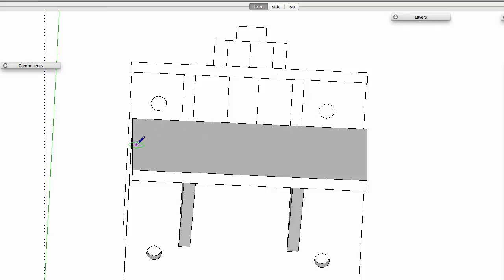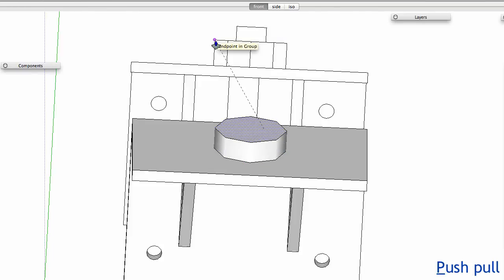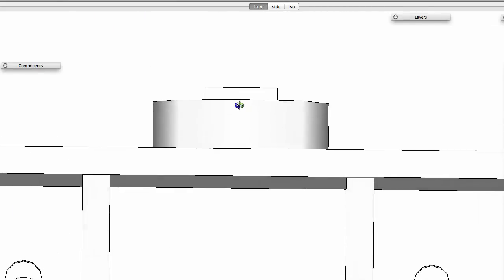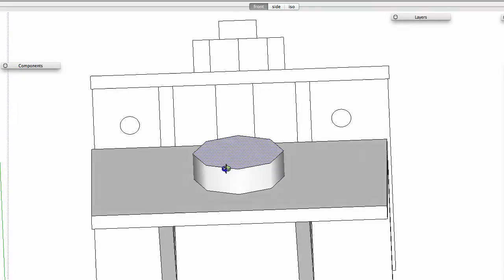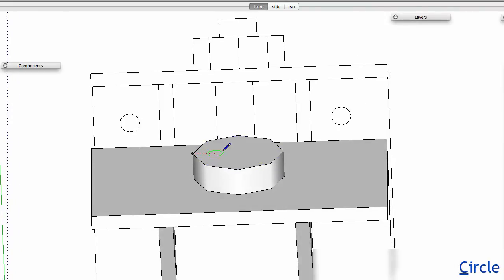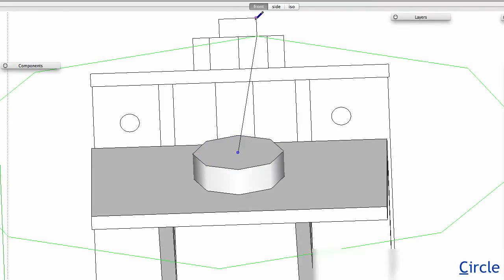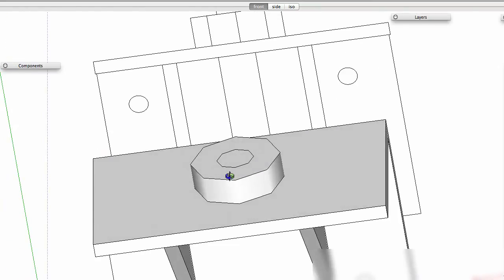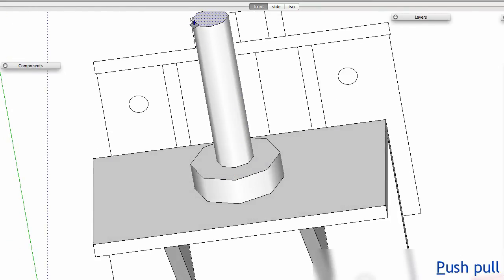Alright, now let's go ahead and draw another circle. Hover, click, hover, click, P to pull, find the endpoint, go to front view. There we go, it's dead on. So let's do the top of the circular shaft. So C, find the center, hover over an endpoint, come back down, draw over until it finds it, infers it, click to place it, then P to pull that up